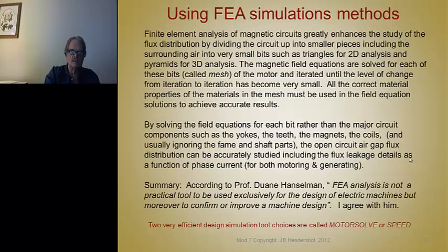According to a well-known professor and teacher of electric machines, Professor Dwayne Hanselman, FEA analysis is not a practical tool to be used exclusively for the design of electric machines, but rather to confirm or improve a machine design. And I certainly agree with him, and I think it's important to underscore this point: many young motor designers will try to begin a design of a motor using a FEA solver, and that is not the way to do it. You use an FEA solver to refine or improve or confirm the design of a machine. But to design a good machine, one must start with a sketch, which we'll talk about soon.